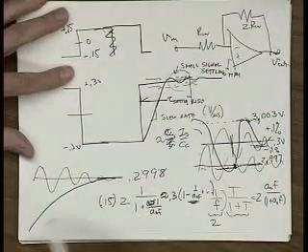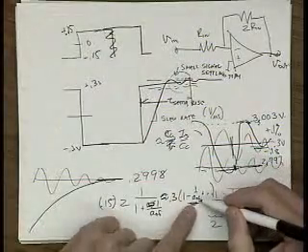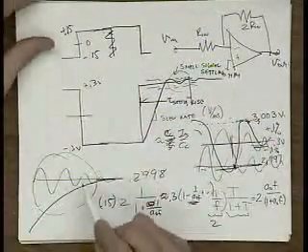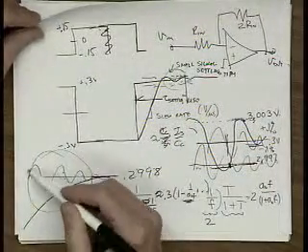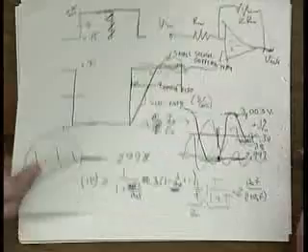It can be doing this as well, right? Now, why don't you want to make this gain really huge? It has to do with this small signal settling. Let me explain that relationship between small signal settling. This is the time after it's gone out of slew rate and it's doing this other stuff.